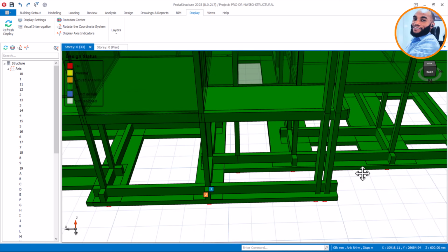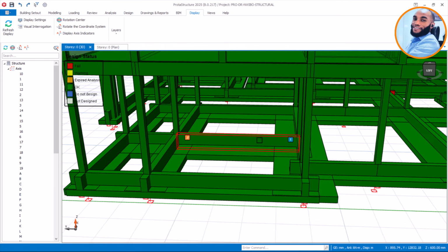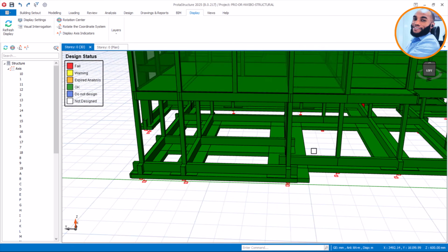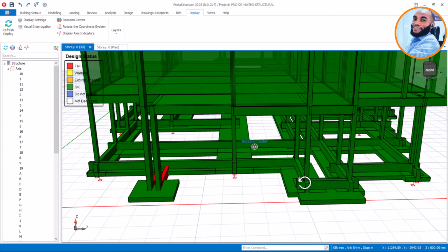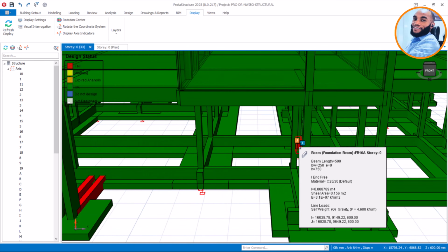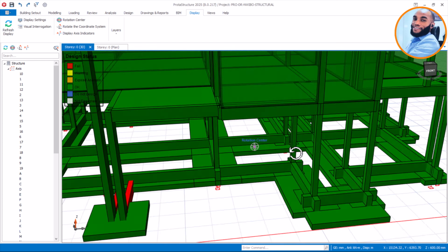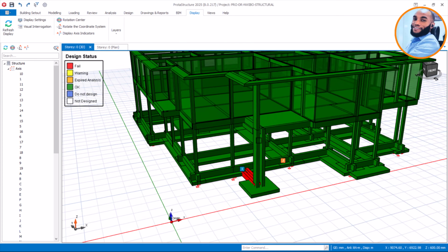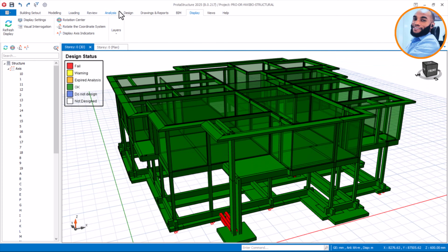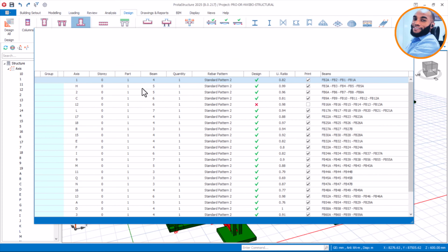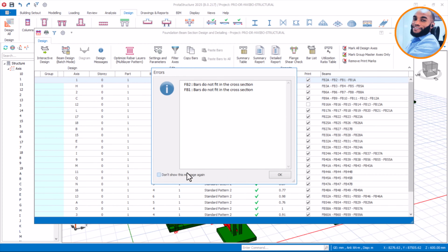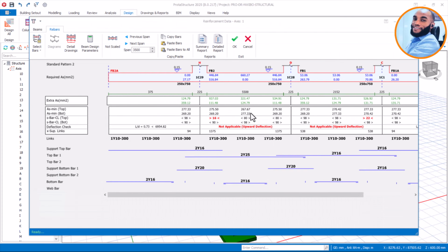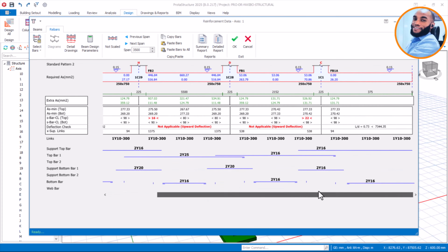So we can check why these beams are failing and why these beams are coloring green, why they are passing. You must question the software. Don't depend on what the software is giving you, but rather you as the engineer need to check the software. Okay, that is fine. So right now you go back to the design here, and then foundation design, and then begin to check each of these particular beams. Okay, I'll just say okay. Now you have to arrange the reinforcement and then correct all these things that are not showing well here. Okay, that is fine.